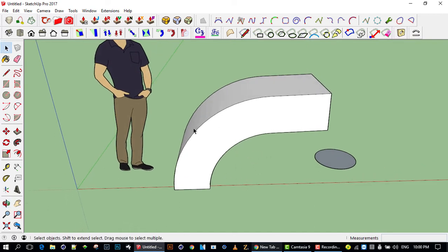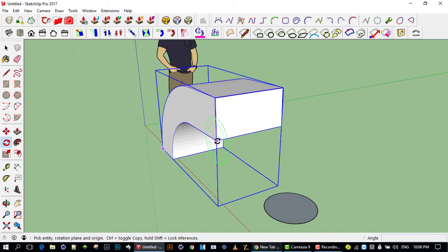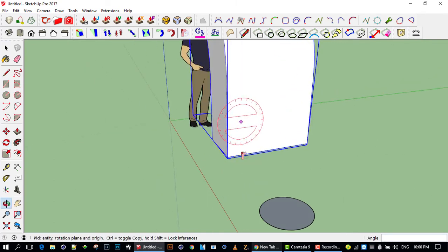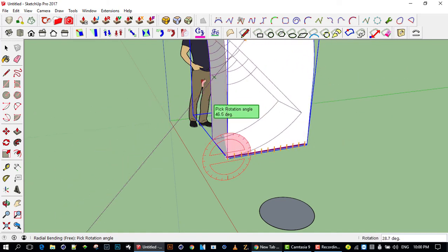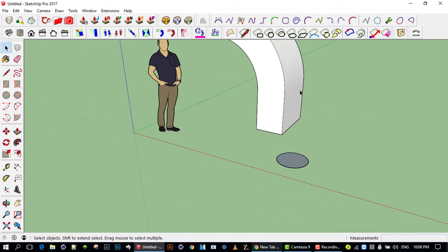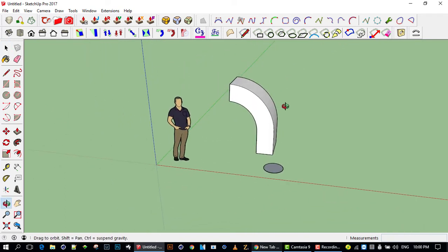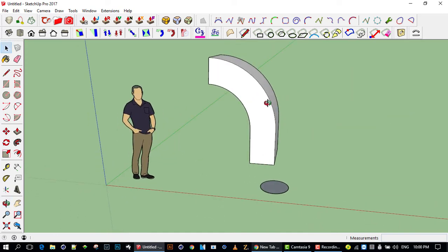So rotate, I can go rotate a model, and T, it kind of works in that same zone. So if I'm here now, I can click R for rotate, select that, and pull it over, etc. Then T, I can do along that way, and do the bend. Okay, I'm doing some crazy bends now, but that's just to show you the R and T are the two keys. And then a thing that I find very important, I never used to use it that much in SketchUp because you get used to working in the 3D space, but it's your views, your isometric view.